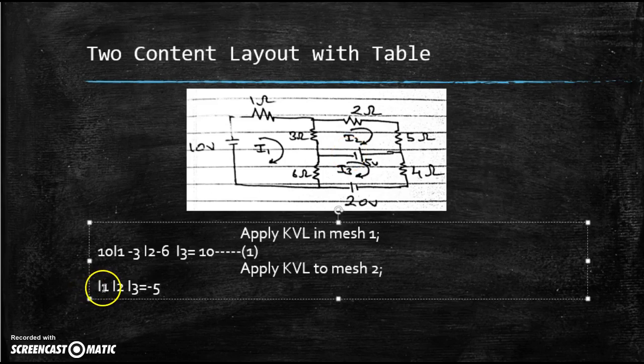Okay. Now let's go to I1. The sign for I1 is going to be negative. The sign for I3 is going to be negative. Okay, and what is going to be the value for I1? The value is going to be the resistor common between I1 and I2. Which is the resistor common between those two? It's 3. Just write 3.